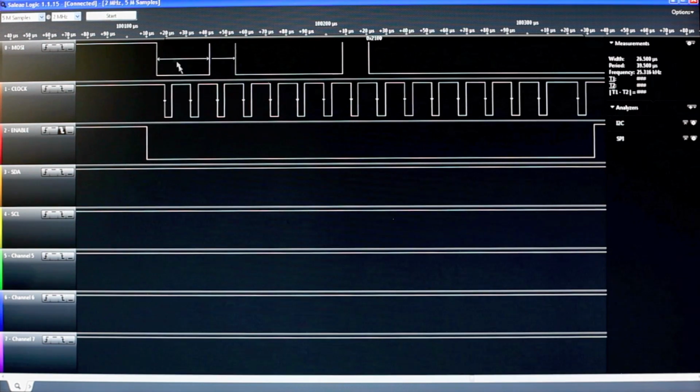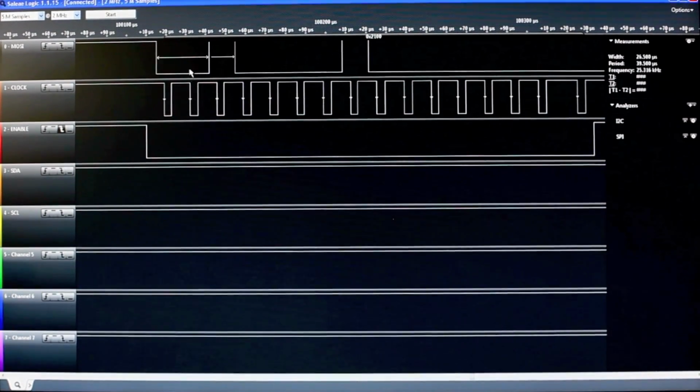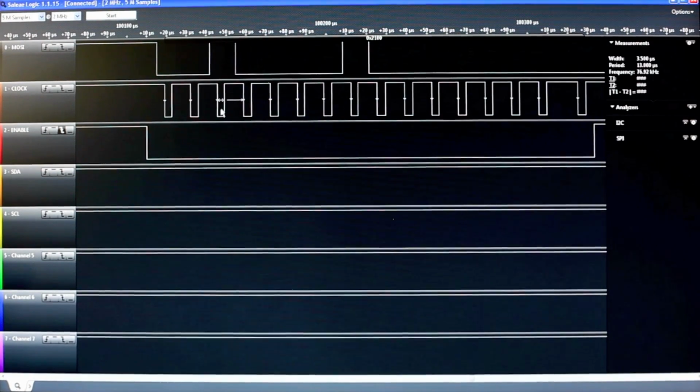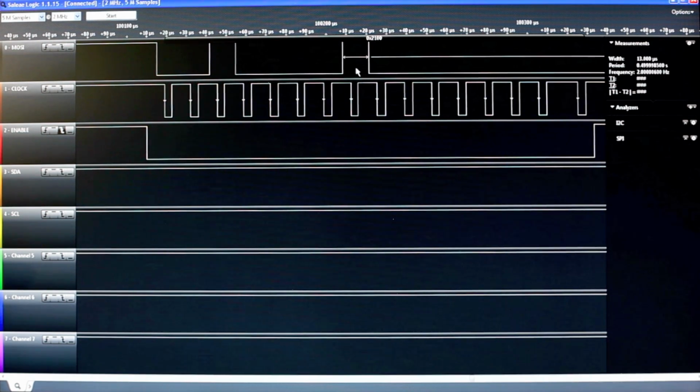So this line goes low, and then the clock goes low after a bit, and it reads the data on the downgoing pulse of the clock. If you look at this, that's a 0, that's a 0, that's a 1, and that's a 0, which is binary for 2, right? Because you get 0, 1, 0, 0, that's a 2. And then you get 0, 0, 0, 1, well, that's a 1. 2, 1. So check it out. And then all the rest is zeros, and it's just telling you up front there.